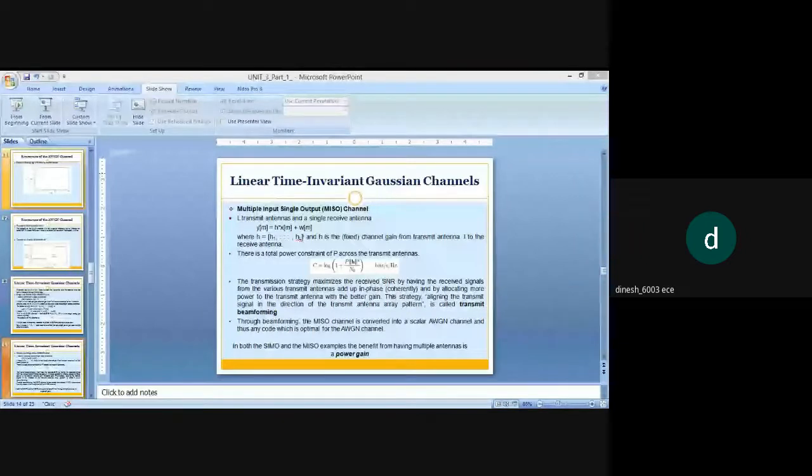Okay, so this frequency selective fading is a transformation to a parallel channel where the time invariant L tap frequency selective additive white Gaussian noise channels will have an average power constraint P on each input symbol, which is given as y[m] = summation l=0 to L-1 h_l x[m-l] + w[m].